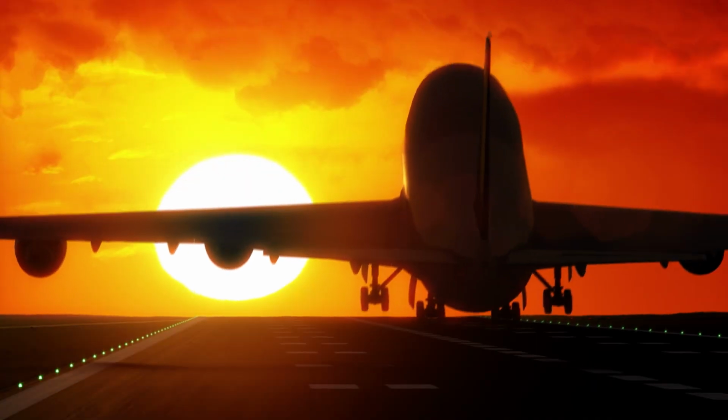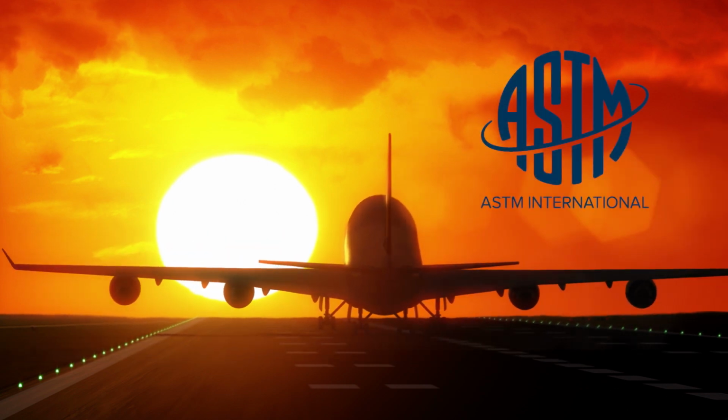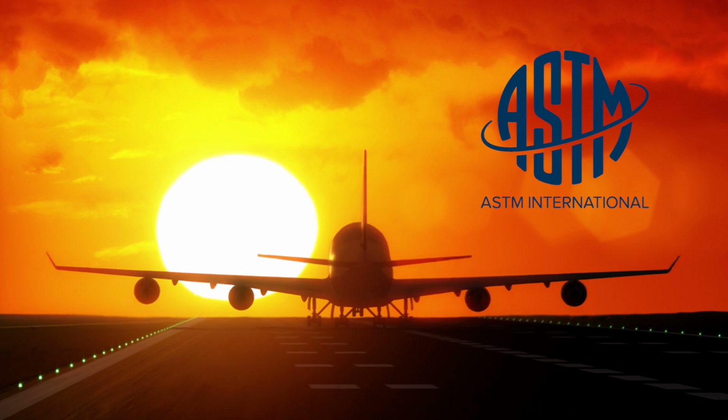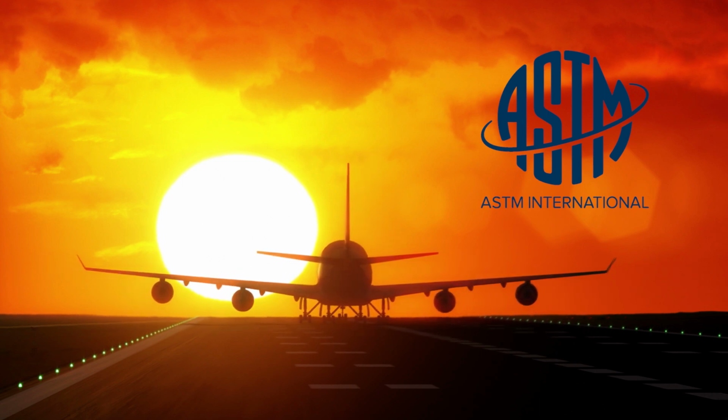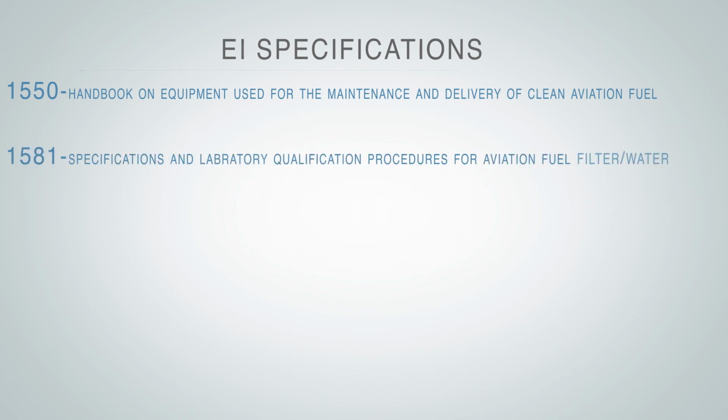Aviation fuel specifications are controlled by the ASTM, American Society of Testing and Materials, and Ministry of Defense Standard 91-91. EI publishes Handbook 1550 for guidance on topics related to aviation fueling. The Energy Institute specification for filter separators is EI 1581.